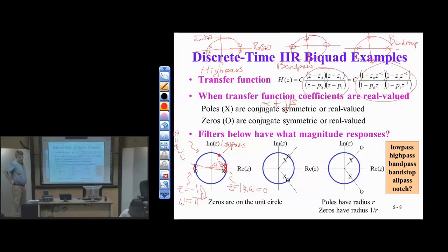All right, now it's getting more interesting. Now the poles and zeros are at the same angle. Now something else is going to happen. Something kind of unusual. So you can reuse your answer in just a second. Okay, it's coming. All right, so this middle one's interesting because if we apply this geometric argument, I know that at this angle, so again, we're at the middle one here. So in the middle choice, if I look at the frequency content at the same angle as the 0, what's the magnitude response? 0 at that frequency. The pole can't alter that.